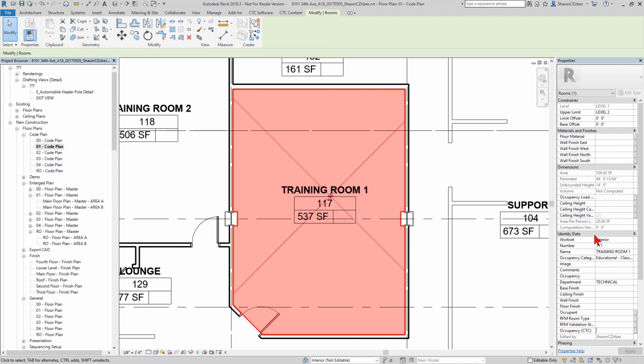What I want to do is take area, the actual built-in Revit parameter called area, and I have my own parameter that I made called area per person. You could also call this load factor or whatever you want, any values that you want. In my case, they're both square foot as area parameters. And I want to take the area, divide it by this, and then round up or down. Do whatever the maths are I want to do. In Revit, again, on the object, can't do it.